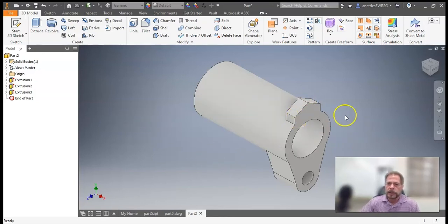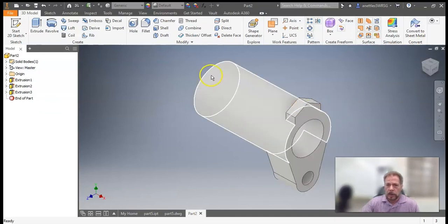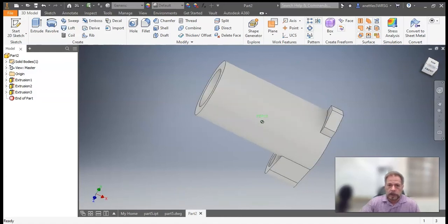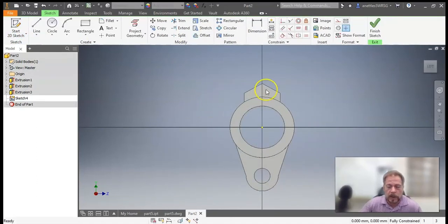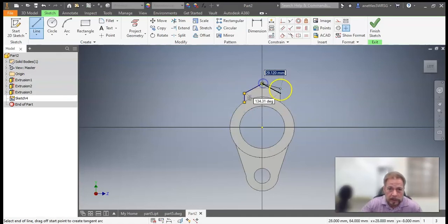All right, so let's draw the... Actually, I'm going to use this to project to make drawing on the other side really easy. Let's draw this part over here. So let's go back to 2D sketch, and let's draw it on this face. All right, now we have everything we need. It's right here, and we just have to grab it. So let's go line, and let's start at the end point of this line, which is projecting from the back. Let's go up to this line, go click that end point, and that end point, and hit OK.